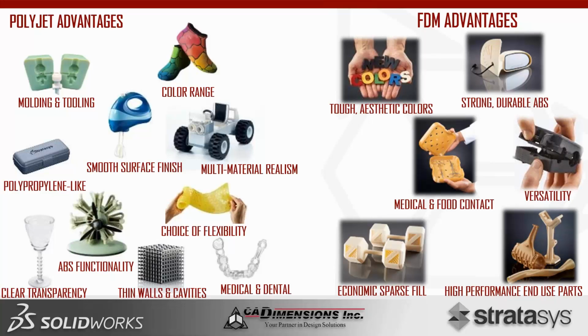With PolyJet, you have anywhere from 32 to 16 microns of accuracy, although with the J750, you have up to 14 microns. And then with FDM, you go anywhere from 13 thousandths of an inch down to 5 thousandths of an inch. Again, it depends on what technology or system you're using, as well as what material you're printing with.